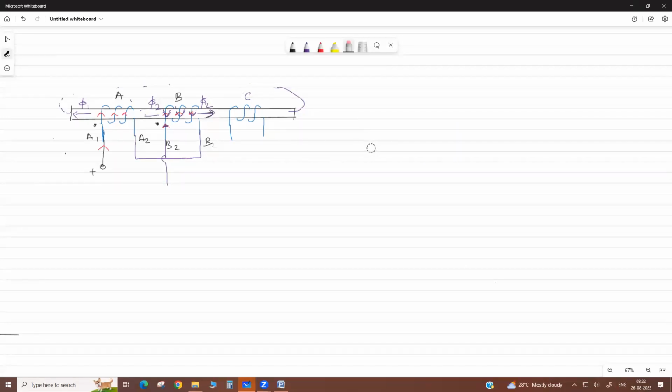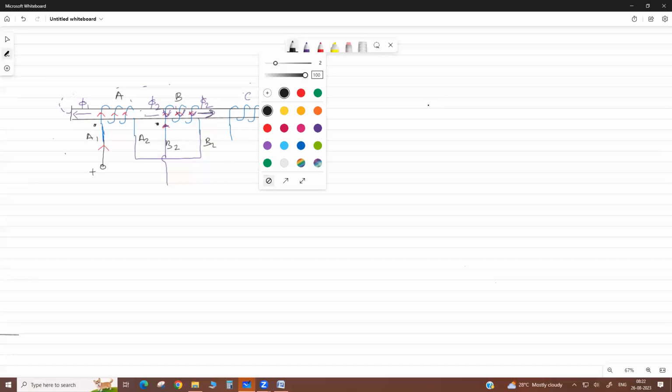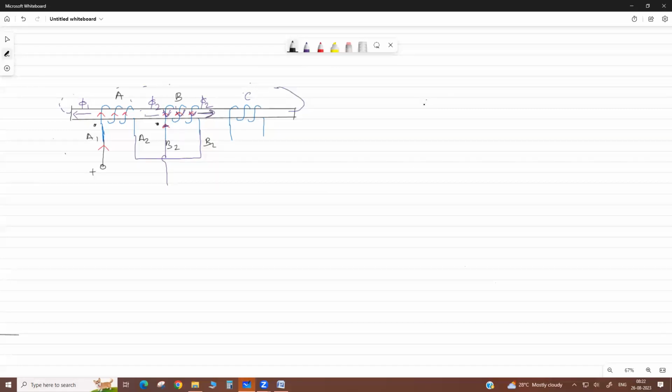By a series lamp we can check how to identify the terminals of a motor or transformer. Either you have an inductance meter or a series test lamp, you can easily see.